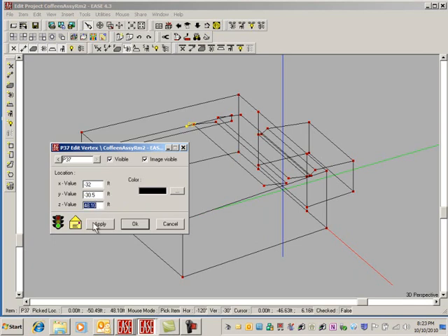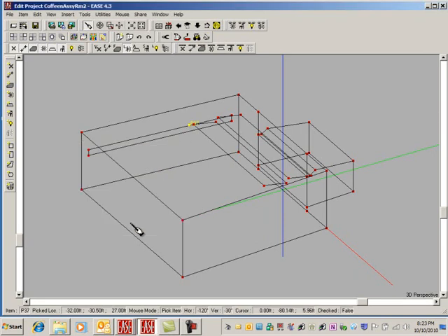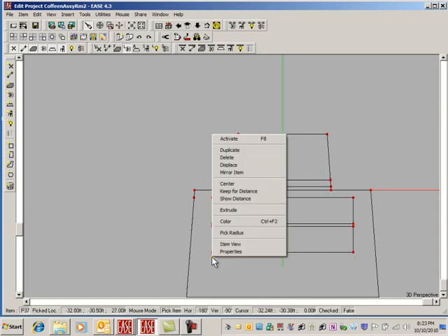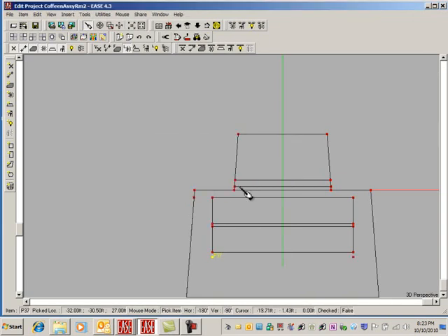Now, we're going to extrude this guy 12 feet, but down in the minus 14 degrees. So say OK. And again, right mouse, extrude. We'll do it over here rather. The horizontal angle 0 and the vertical angle minus 14. Do this in polar coordinates. Distance is 12. Okay. There's our next panel. Let's look at it here. There it is. Looks good.